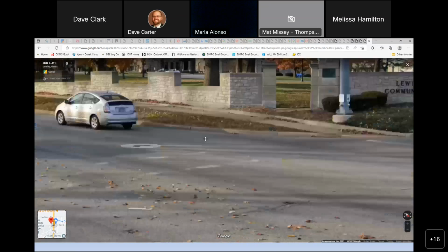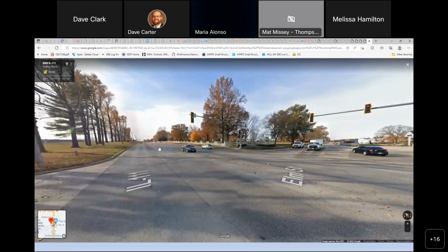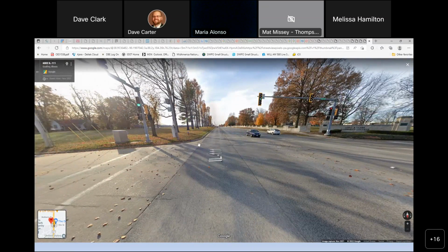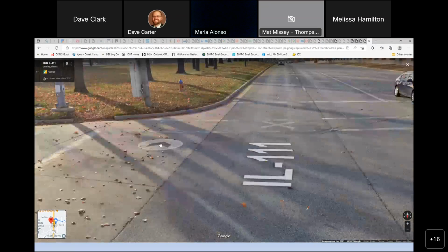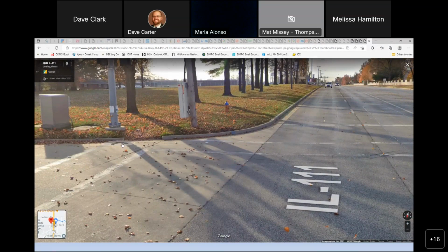One thing that I did notice here is they didn't show any improvements here. And as I'm thinking about that, there's a curb cut here for something, but it doesn't appear there's anything there. Normally, if they have a handicap ramp and a crosswalk coming across here, they have to build something here. Even if it's just a landing, whether it goes anywhere or not, a landing where a handicapped person can get off the roadway and be in safety. So that might be something that gets added to this project. I don't know.